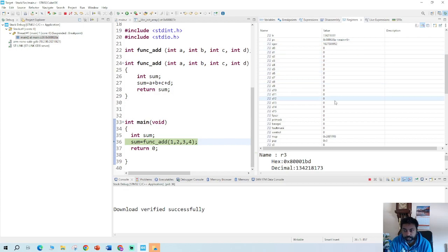By this time the processor will ignore the PSP, but you can allocate the PSP to the stack pointer by initializing it either before the main program or inside the main program.